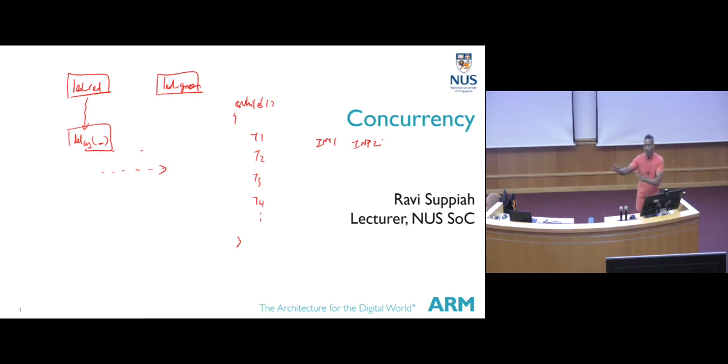Now we can still have all of that, but we change the whole architecture of how the code is designed. Instead of saying I run task 1, task 2, task 3, task 4 in sequence, I am now going to say that each of them is an independent task that is going to handle something for me. One can handle motor control, one can handle LED control, one can handle the UART interface, one can handle audio. So now instead of thinking sequentially, you think of everything in parallel.